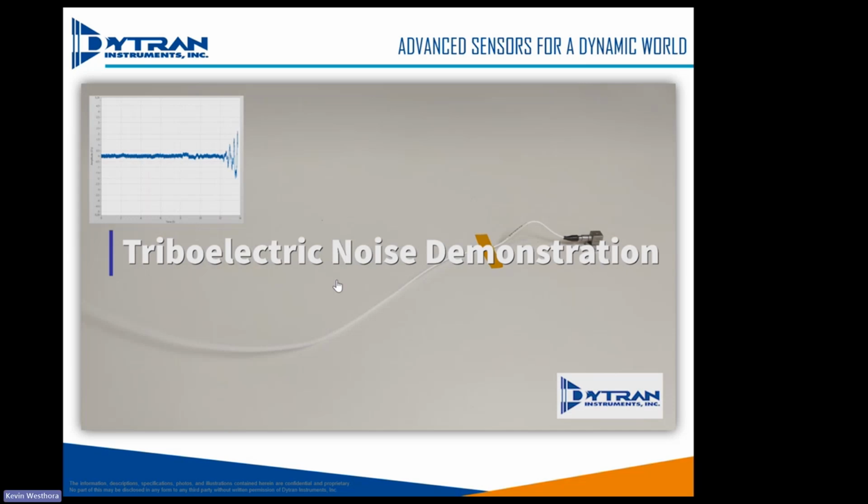So I want to talk a little bit right now about triboelectric noise. Triboelectric noise is noise from your sensor cable, not the sensor itself, but the cable. And this demonstration has a charge mode accelerometer with an IEPE cable. So it's important to know that each sensor, voltage mode and charge mode, requires specific cables. If you have an IEPE sensor, you need an IEPE cable. If you have a charge mode sensor, you need a charge mode cable. And this is what happens if you don't do that.